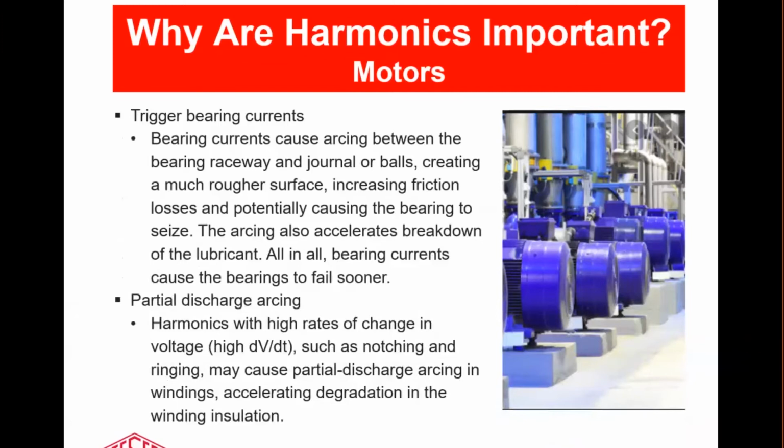They also have another effect, and that is they can cause arcing between the bearing raceway and journals or balls, which creates a rougher surface, which increases vibration and friction losses, and this can lead to the burnout and breakdown of bearings.